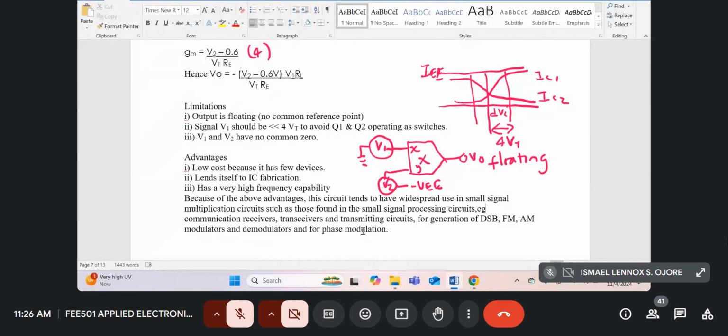Multiplier circuits are also used for frequency translation. If you multiply two cosine waves, you get the sum and the difference of the two cosine waves. And they're also used for reception. They can be used for demodulation. So I'll just stop over there for now. There's a lot that can be said over here. Most of the modems that we use for both modulation and demodulation use multipliers, but not this one. This one we've shown. There'll be four quadrant multipliers, which will be our next topic.